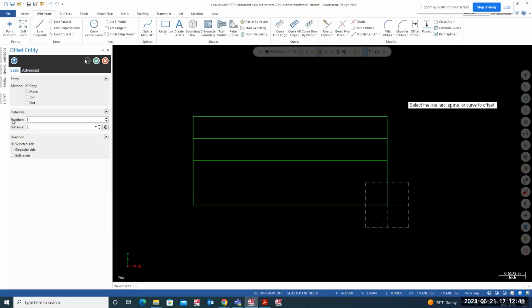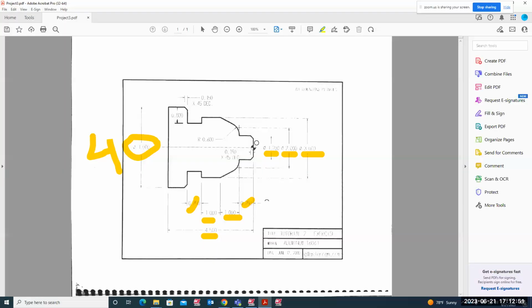We're going to offset half of that, 0.6. And there is 0.6 offset. Hit OK. So basically, I offset these lines here, 0.6, half of that, which is 1.2, half of that 0.6, 2 inches, half of that, which is 1 inch. I offset that line. And 3 inches, half of that 1.5, I offset this line here. 1, 2, 3, we offset 3 lines.